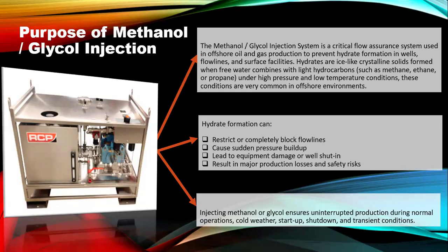And then these conditions are very common in offshore. So I think we've discussed this a lot of times, how these hydrates have been formed. Hydrate formation can restrict or completely block your flow lines, cause sudden pressure buildup, lead to equipment damage or well shut-in, and result in major production losses and safety risk.